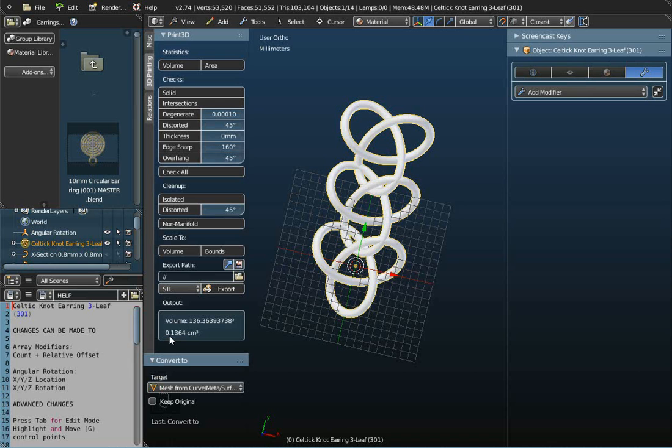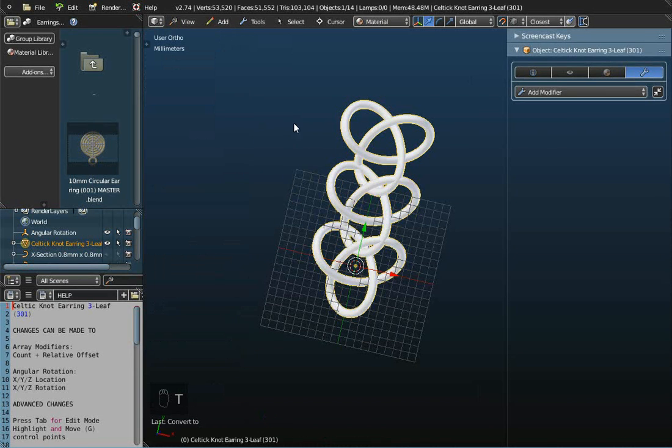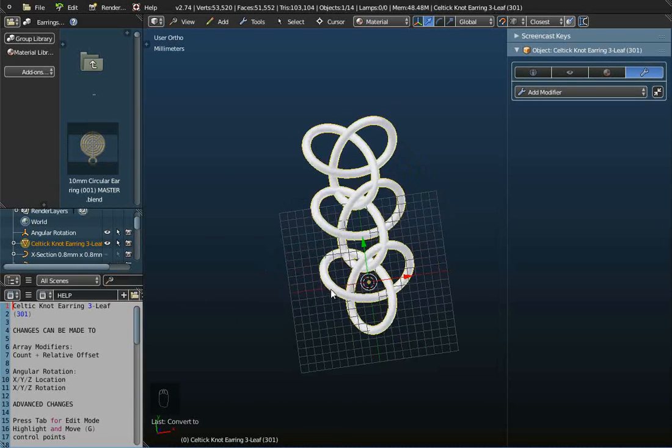And what you need to do is count the decimal point back 3 times, 3 times and 3 times. Count it back 9 times in total, and then read off the volume. In this instance with this object, no problem, that's the actual volume. So we can close the toolbox down now, and I'll just press the T key on the keyboard to do that. Now what I want to do is I'm going to actually add a connector to this.